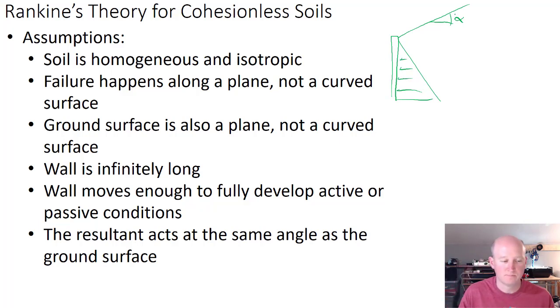because of the backfill. And so Rankine's got a theory, and we want to try and use Rankine anytime we can because it's relatively easy to use, and I'll show you the equation here in just a second. We're going to calculate K a little bit differently. But we need to go through what the theory is and what the assumptions are so that if we are not able to follow these assumptions, then we have a problem.